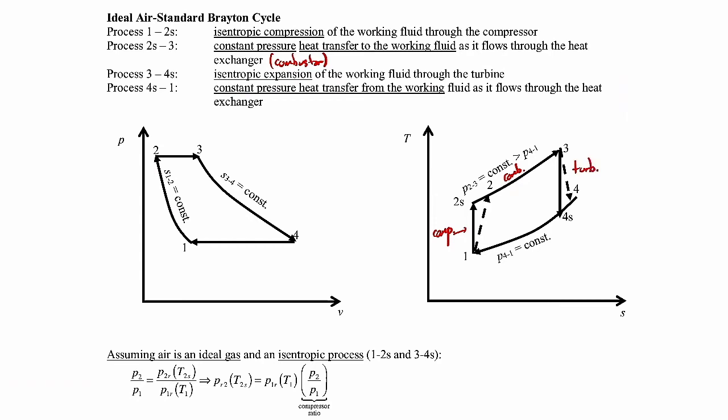So we're moving through the turbine here, so that's this part. And again, if it's an ideal turbine, 100% isentropic efficiency, we go vertically straight downward. You can see, S3 equals S4s. Same sort of thing over here. In the real case, we would be moving off to a little bit higher entropy if we had less than 100% isentropic efficiency. So when we go from 2 to 3, that's along the same isobar. When you go through the turbine, the pressure decreases. So we're now back on this isobar, so the pressure is less. And you can see that over on the PV diagram.